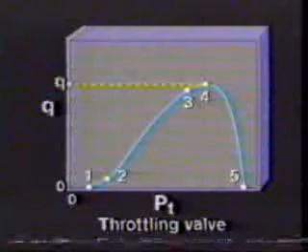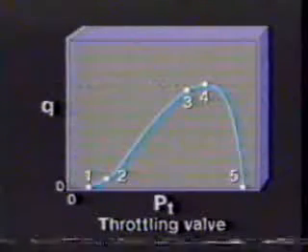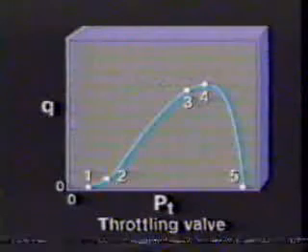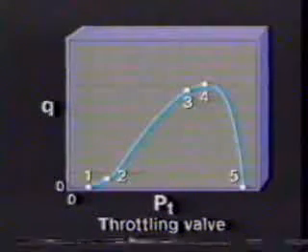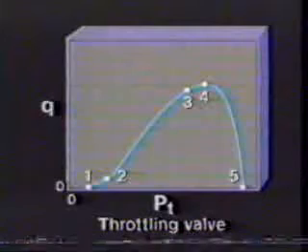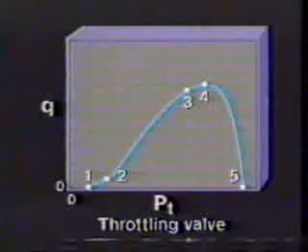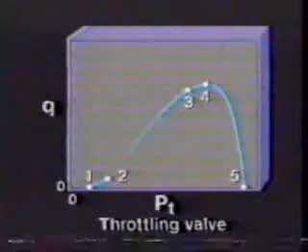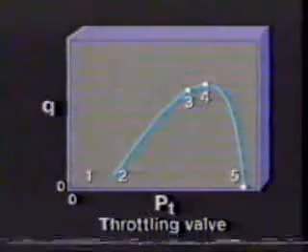As the tubing pressure increases from point 4 to point 5, the tubing and casing pressures become balanced and the flow rate drops to 0. During the reverse cycle, as the tubing pressure decreases, the valve opens at point 5. Throttling takes place between points 3 and 2, and the valve throttles close between points 2 and 1.